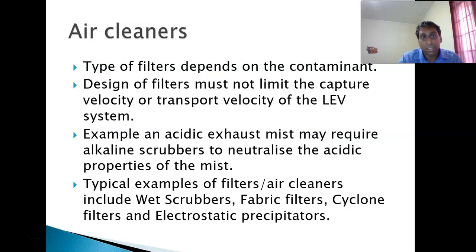The type of filter depends on the contaminant. The design of filters must not limit the capture velocity or transport velocity of the LEV system, meaning that the filter shouldn't put extra strain on the system. It should be of a suitable pore size and whatever have you. For example, an acidic exhaust mist may require alkaline scrubbers to neutralize the acidic properties of the mist. Typical examples of filters or air cleaners include wet scrubbers, fabric filters, cyclone filters, and electrostatic precipitators. So these are quite good.